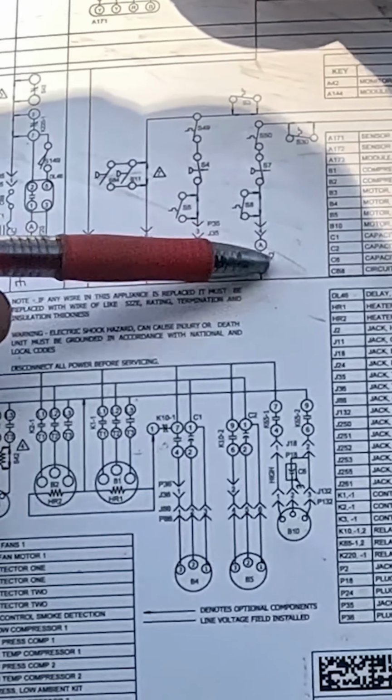But then we land on K2, contactor coil. In all actuality, it's actually this one because things got reversed. This should have been over here, this should have been over here. Factory mess up. This relay is normally clear, but this one's very, very darkened, so we're going to have to quote them a new relay.